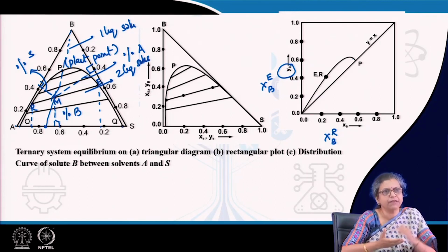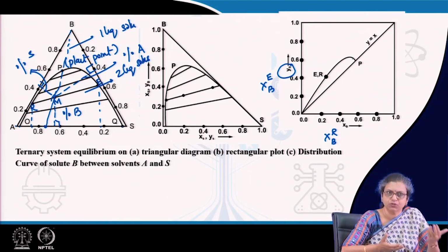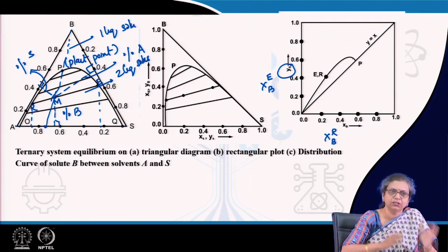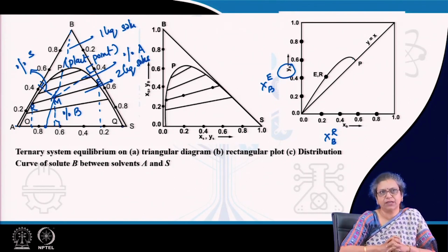Just like we have equilibrium ratios or K values for distillation, we have the distribution coefficient for liquid extraction cases. Just like Pxy, Txy, and Xy, they are important for distillation. The Pi versus Xi curves are important for absorption. Q versus Ci or Q versus Pi curves are important for liquid solid adsorption and gas solid adsorption respectively, and the ternary plots are important for liquid extraction.